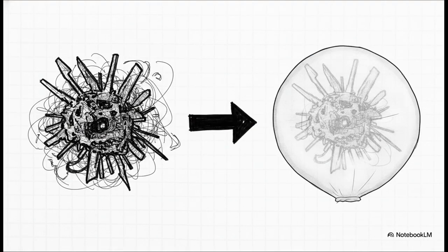And finally, step 3. For CAD models with overwhelming artifacts like crazy self-intersections, cracks, or just extreme complexity where cleanup is basically impossible, that's where the Wrap Surface tool comes in. It creates a simplified, meshing-ready envelope around your entire model.